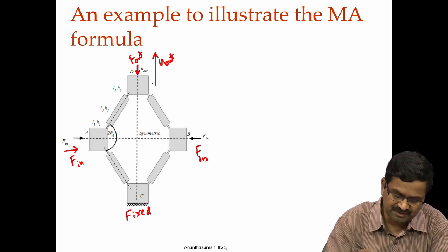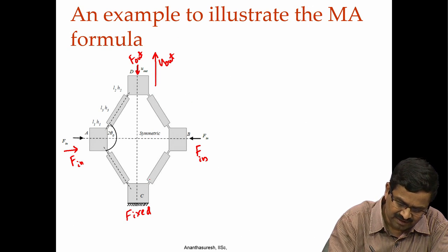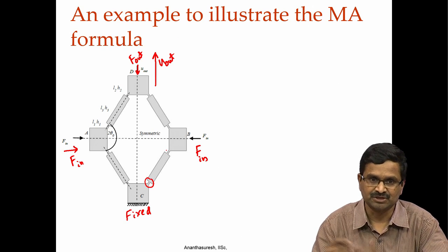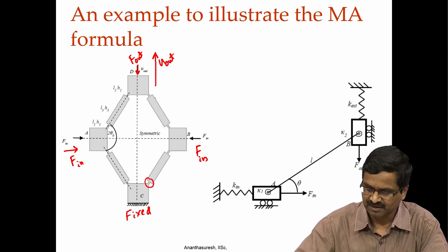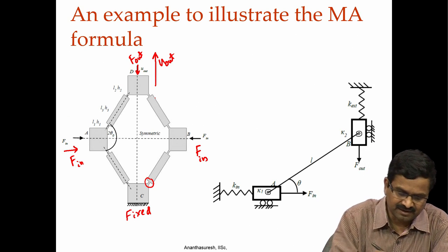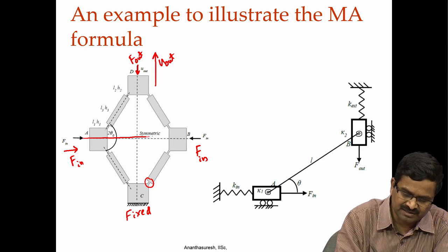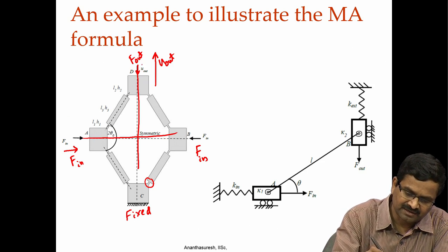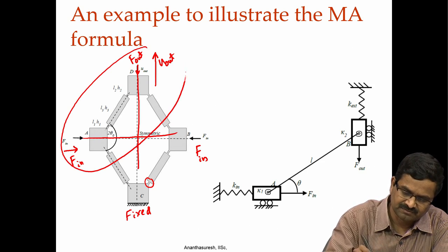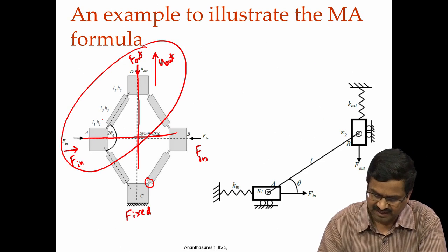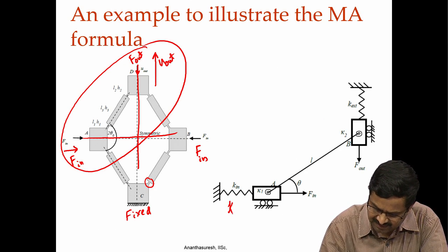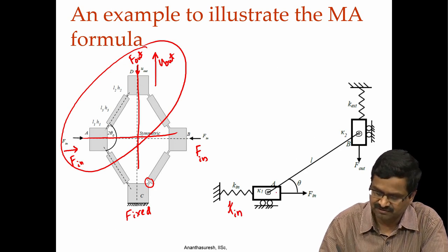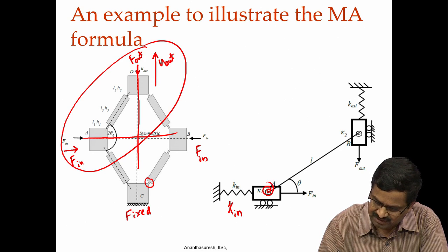So, such a compliant mechanism, here we have taken something simple where there are these flexural pivots, which is not a great thing, but for an example we have taken this. So, for this we can make a model, that is I can take the symmetry. So, I have symmetric axis this way and that way, I can take only this portion. If I take only that quarter, then I can show that there is some K in here, there is a translational stiffness and there is also a rotational stiffness here, that is kappa 1.